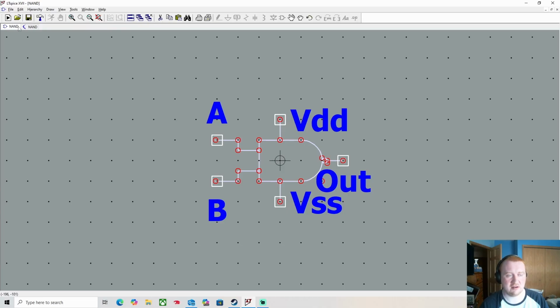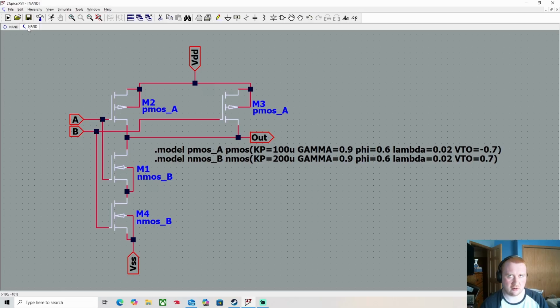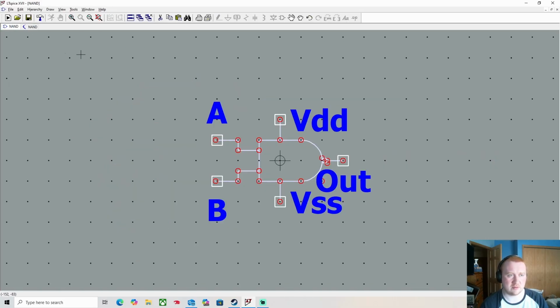I forgot to mention in that other video that the other method, the netlist method, will be pretty much compatible with any SPICE simulation program. There might be some adjustments you have to make, because I don't know if LTSpice has special flags or not, but that method is supposed to be consistent across all SPICE. So that's another huge difference between these methods. This method won't work on other SPICE programs because this is specific to LTSpice.